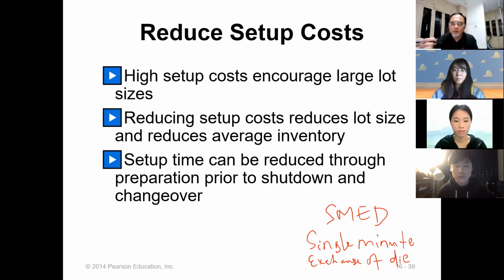Die here means tools. Setup time depends on how much you can change from one production to another, for example a part changed to a new part, or to a new stamping process. So setup time must be reduced by using this technique, single minute exchange of die.